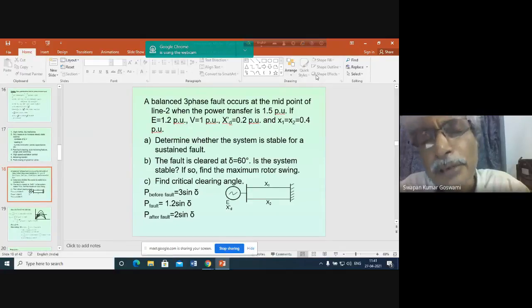Then the field winding current, the additional current, will take somewhat more time. So initially, during the transient condition, when the damper winding current is flowing, the reactances will appear to be much less. But gradually it will increase as the damper winding current decreases. So after 3-4 cycles, the damper winding current will die down completely, and then the reactance will change, because the same field winding current is still there. So the field winding current will sustain for some longer time.